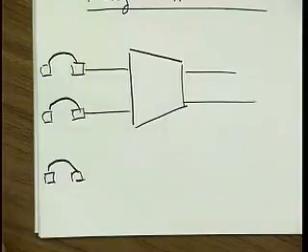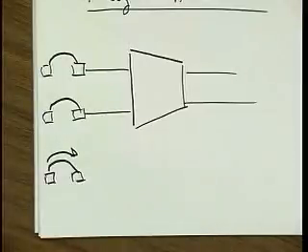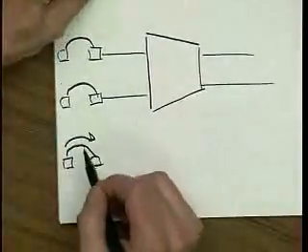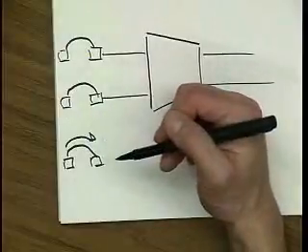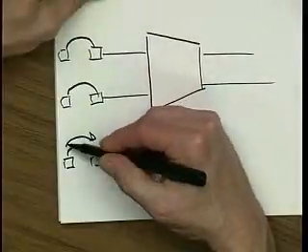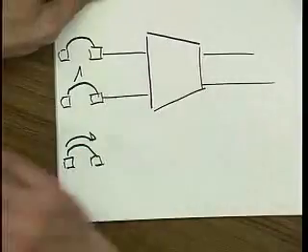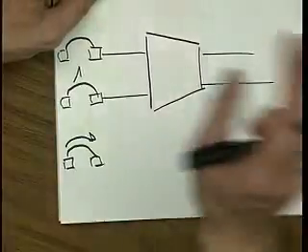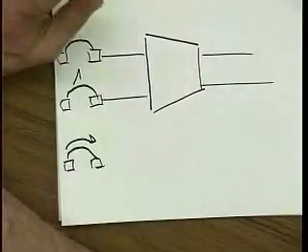But the short circuiting of the power supply basically means that there is a huge spike of current rushing in, and then things get nice and quiet again, and then they short circuit the supply again. It's really awful if you think about it. But the digital folks, they rule, right? So they do that, and this thing here looks like a transformer, and so it is one. So this large DIDT produces a voltage spike appearing across this wire here. And that just goes into a sensitive A to D converter, and it's not going to be very good.